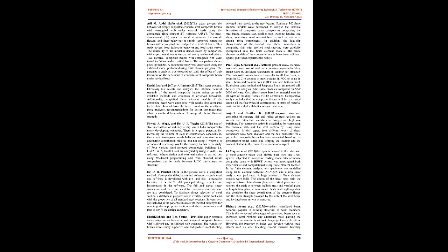E. Hosseinpour and Ben Young, 2014. This paper presents an investigation on behavior and design of composite beams with stiffened and unstiffened web openings. The composite beams were simply supported and had profiled steel sheeting oriented transversely to the steel beams. Nonlinear 3D finite element models were developed to analyze the inelastic behavior of composite beam components comprising the steel beam, concrete slab, profiled steel sheeting, headed stud shear connectors, reinforcement bars as well as interfaces among these components.